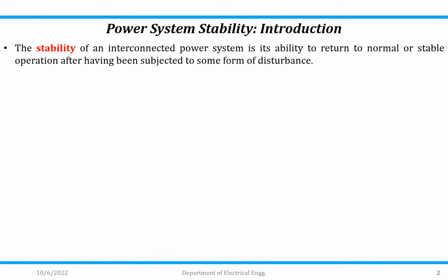The system must be in a position to adjust to the changing conditions and operate satisfactorily. The system must withstand large disturbances which may even cause structural changes due to isolation of some faulted elements. It is impossible to design a system which is stable under all disturbances. The power system is generally designed to be stable under those disturbances which have a high degree of occurrence.